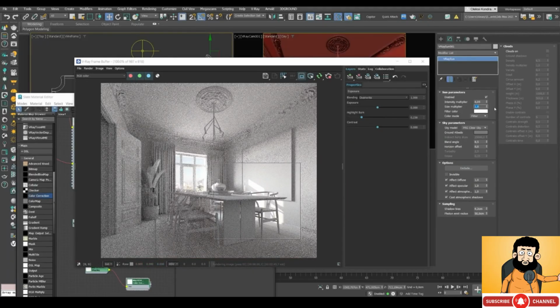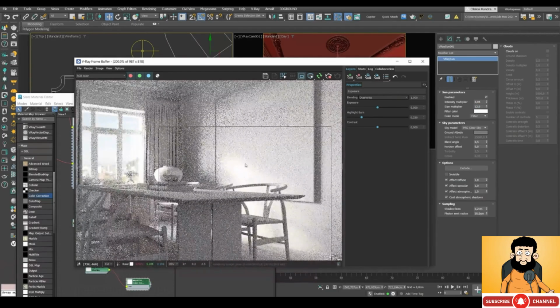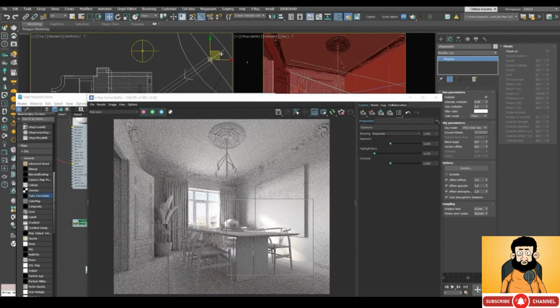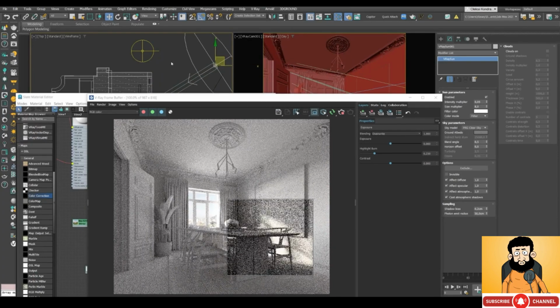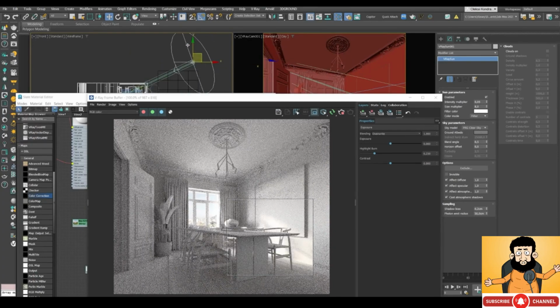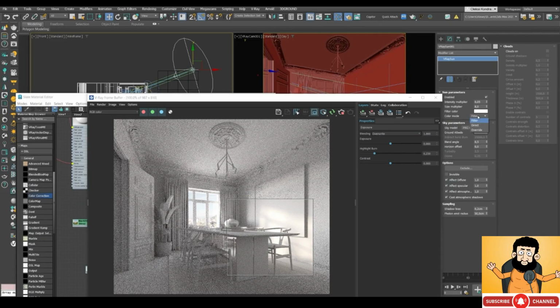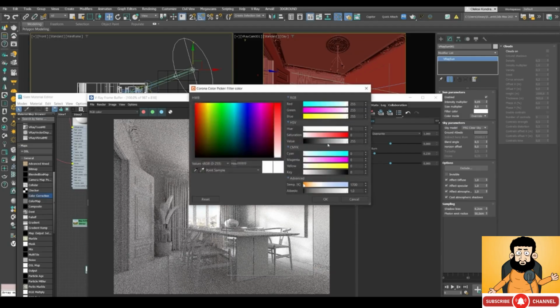Let's go ahead and blur it. We'll set the size multiplier value to 12. And I think we can even reduce it further. Let's make it 8. And now we can adjust this light beam. For example, let's direct it deeper into the room. We'll set the sun a little lower. Now, if it's too red, we can change the color mode to override. And here, in override, we can set the value we want. So let's go like this.